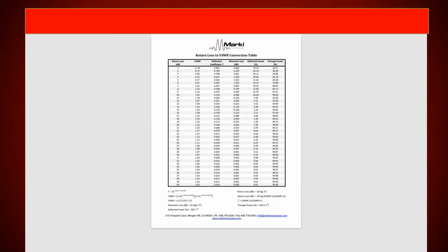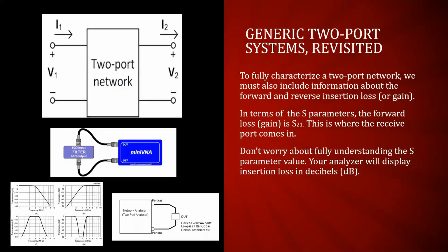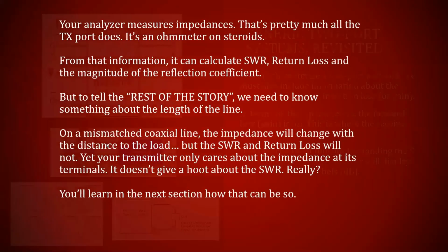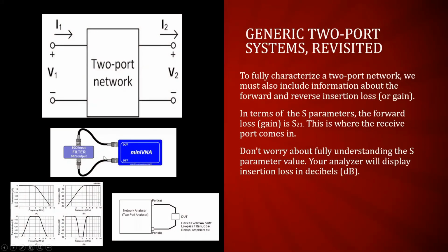All right, so that's enough on the TX port. I'm just going to do a very brief talk about the other port here. And the other port is the receive port. Here's your transmit port, here's your receive port. And if you want to measure the insertion loss of a filter, the way you calibrate is you take a jumper between these two ports and you calibrate out that,